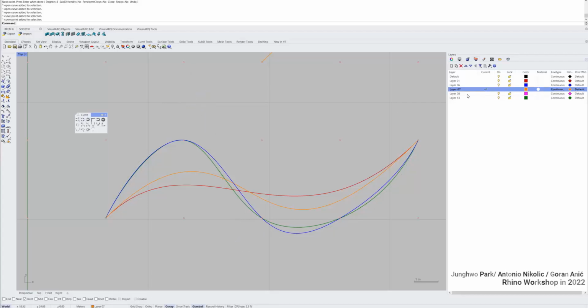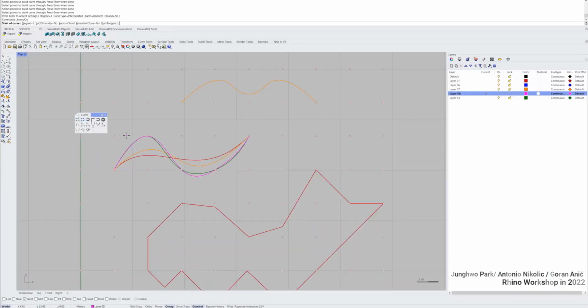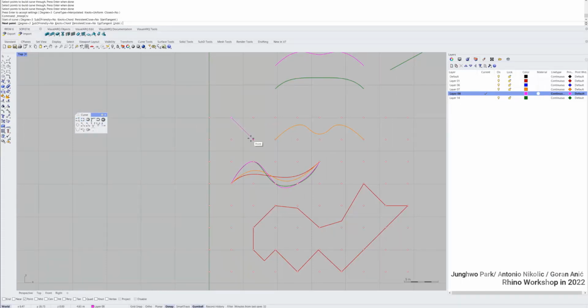If you compare the first option with the mouse right button, and we select these points with degree 3, you get the same result actually. For the first icon on the mouse right button, you have to select the points and then it will draw. But with the second one, we can select the points while we are drawing the curve.